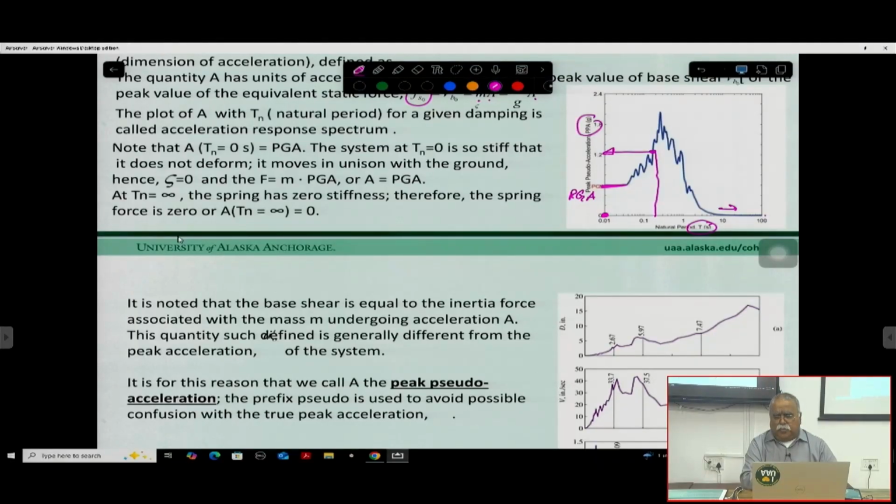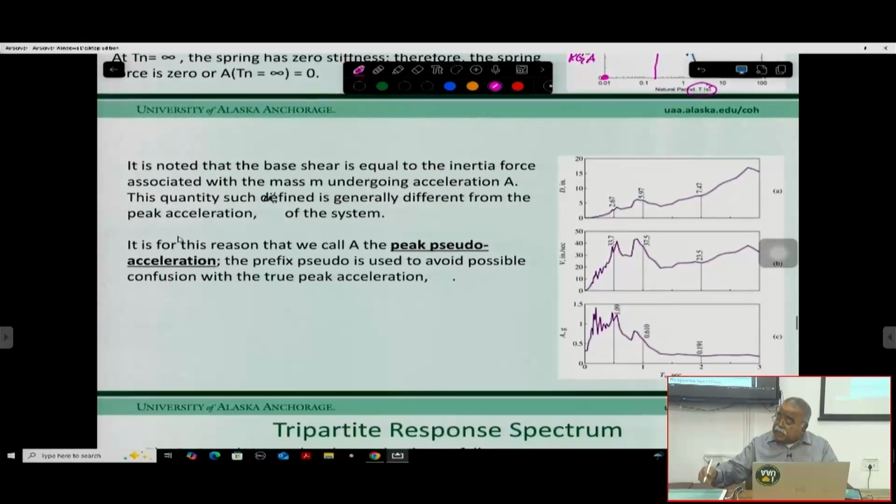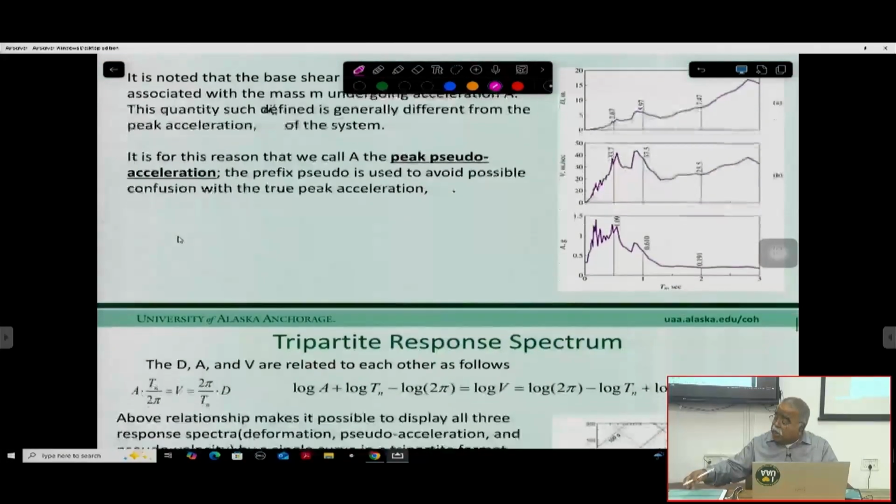So that means for your ground acceleration, you first calculate the response for different periods. Your building will have a particular period, so that value you know. If you know that value, then you can calculate what the response spectrum value will be, the SA value or SD value or SV value, PSV value. You can calculate all of those based on that. Okay, so that's the thing we need to do first.